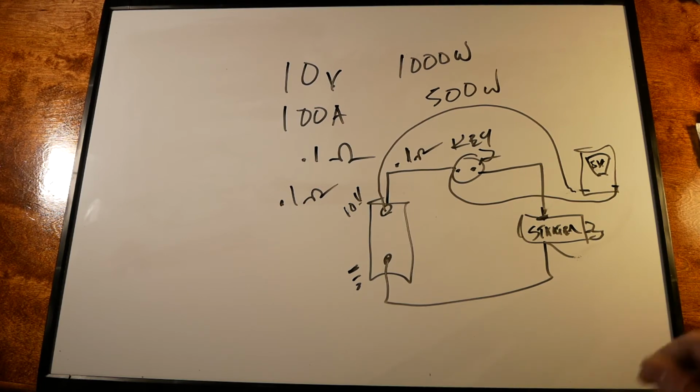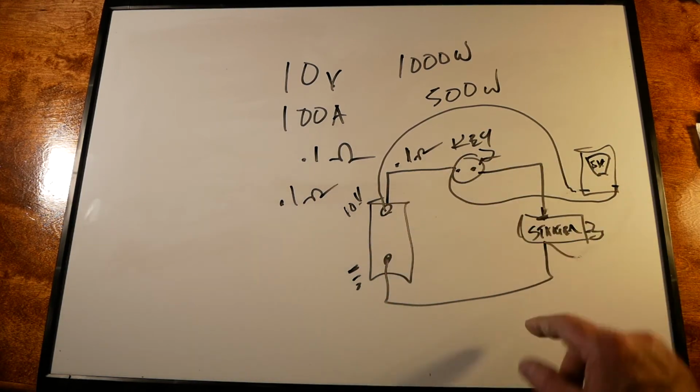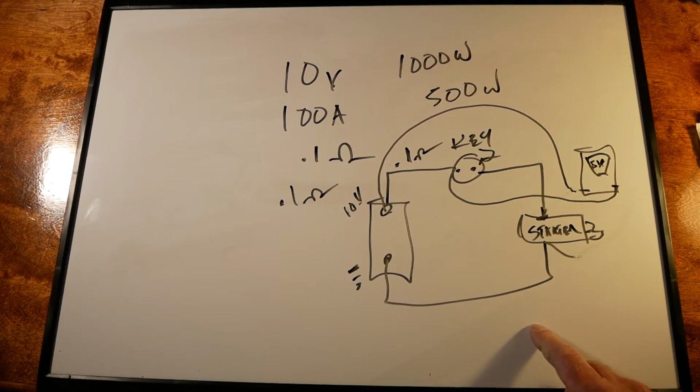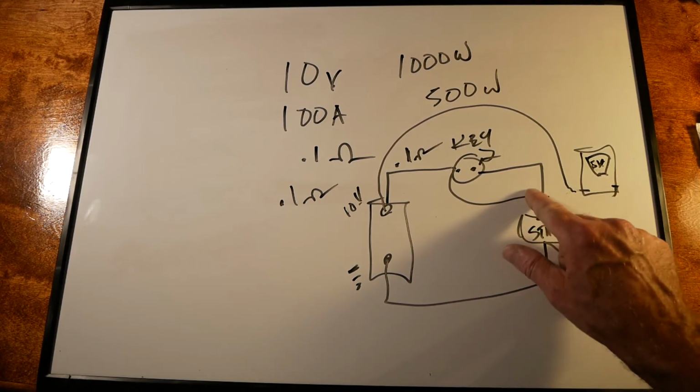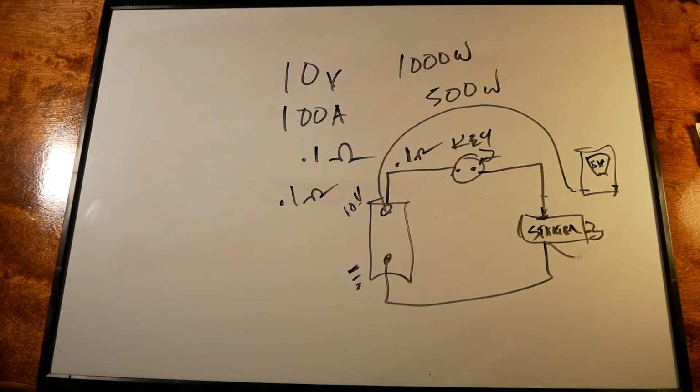This is one of the reasons you can't really use a DVOM on ohms to measure battery cable resistance, because most meters, especially auto-ranging meters, aren't very accurate at such a low resistance value. They're not really reliable measuring such low resistance values. So you can use this method to check the voltage or check the resistance of the circuits going to a high current device. In this case, and I've done this many times, in order to check the resistance of a